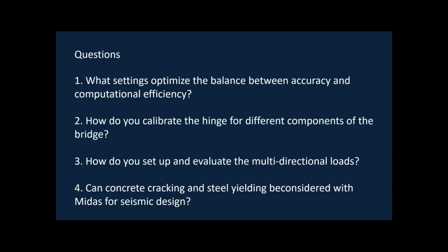For considering these, we need to define a fiber model, and the simulation of the fiber model can be done in the nonlinear time history analysis. The third session that we are having will consider the fiber model, which will capture the cracking and the steel yielding in the seismic analysis.